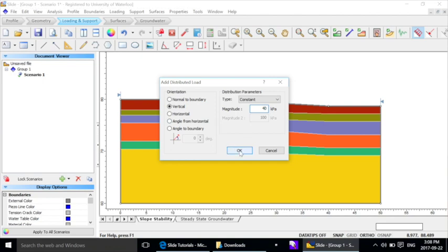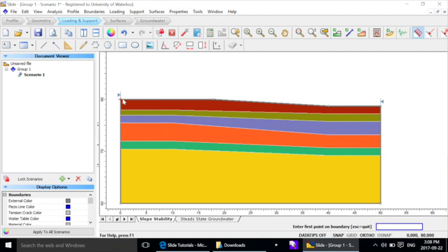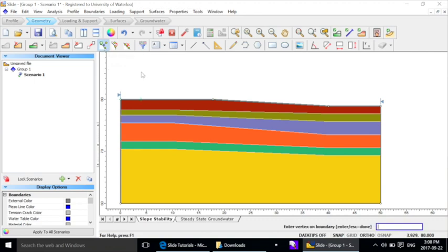Okay, and this vertical load is going from 0 up to 10. You could do it by hand, like this. A good approximation is a good idea. The other option is to include a vertex, like this. Modify the geometry, include a new vertex, and this vertex is going to be 10 and 80.